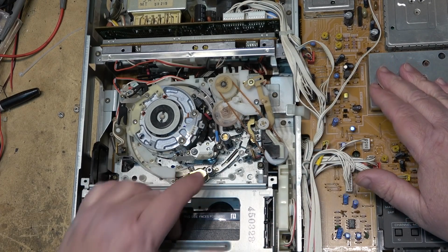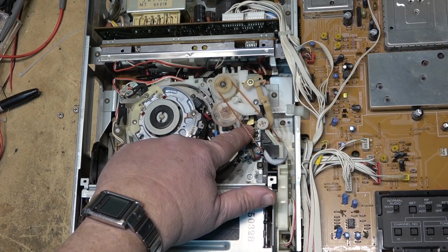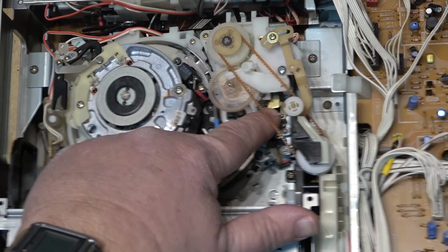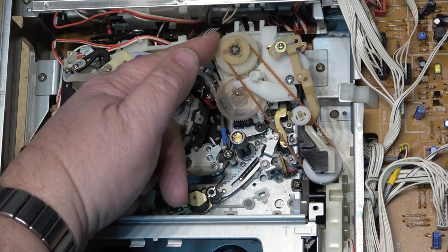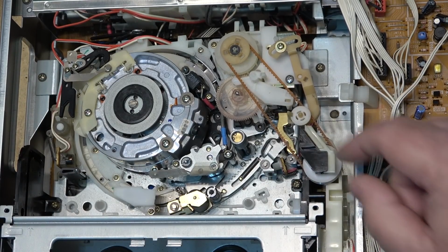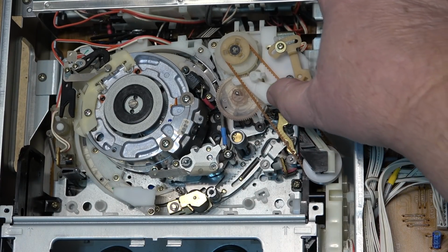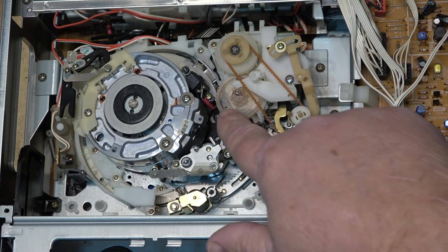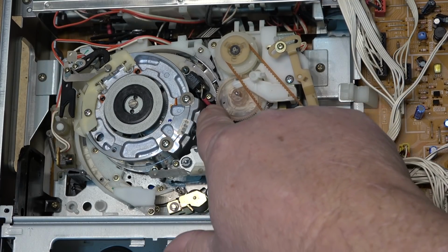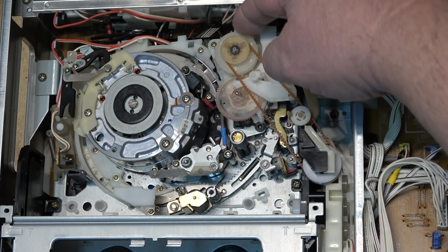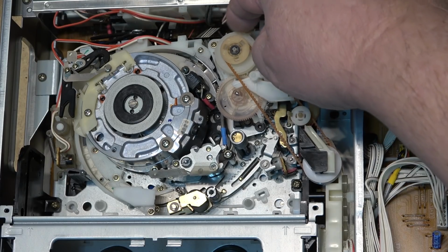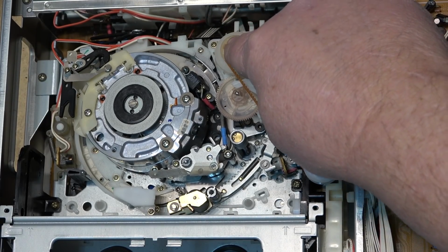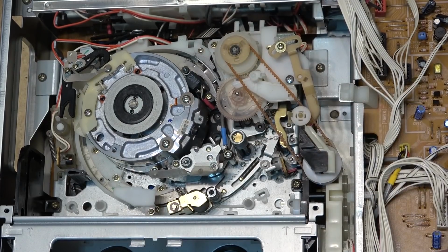And then what you'll see happen is the solenoid here is going to release. The motor's going to come on again, and now the power, instead of it being sent to this outside gear here, because you see the teeth on the power split device here. In this position, it's going to lock this gear from turning, so this gear can't turn. So then the power is all going to go into this outer gear. The planet gears are in here, and the motor is actually turning the sun gear, which is below.